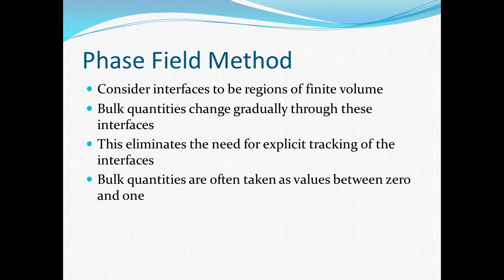Let me first introduce sharp interface model. When we simulate the growth of the eutectic, we can choose either sharp interface model or phase field model. When using sharp interface model, the interfaces are treated as infinitely thin surfaces, that is, they have no volume. By doing this, the interfacial location must be checked at every time step by markers. This makes meshing extremely difficult, which means it takes lots of effort building the model and simulating the process.